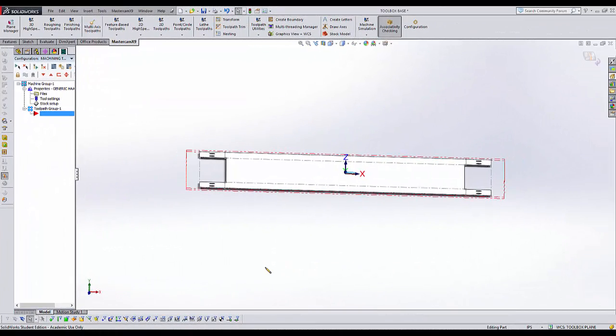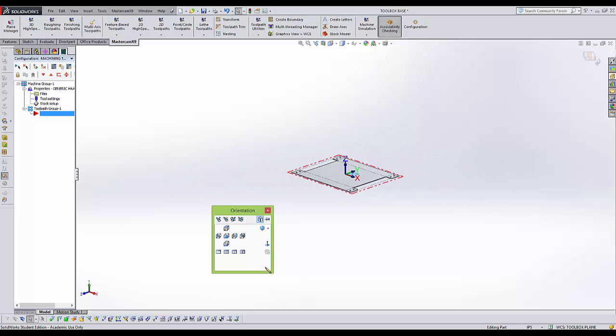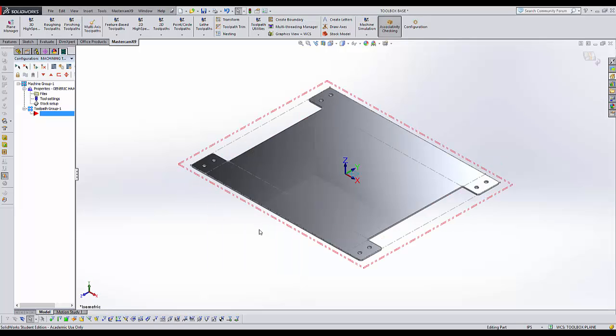Now let's get ready to machine this. We'll put it in isometric, we can see this a lot easier. We see our axes are correct. My X is going this way, my Y is this way, and my Z's this way. Very important, the layout of how we have it here must lay out on our machine, and our machine must be capable of cutting this size of a part. Let's get started to machine. We're just going to use a basic 2D contour to complete the toolbox.